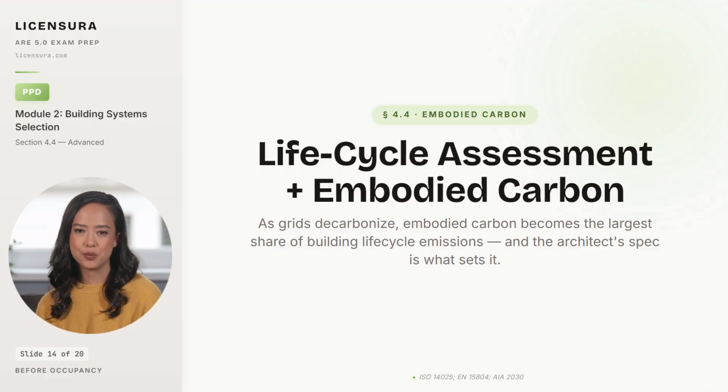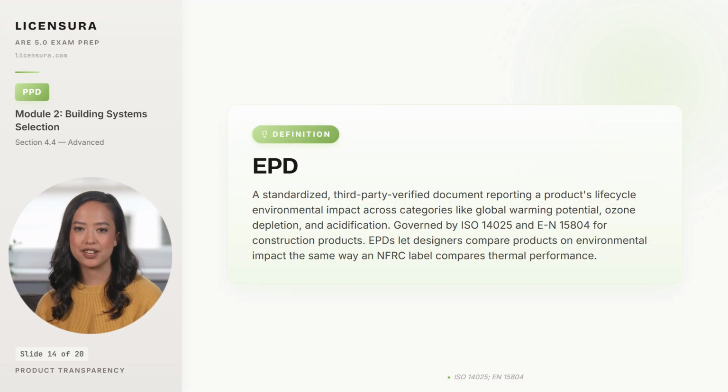Before anything else, one acronym does the heavy lifting in product comparison. The Environmental Product Declaration, abbreviated EPD, is the single document that makes comparison shopping for low-carbon materials possible. Without an EPD, every manufacturer's marketing claim is unverifiable. With an EPD, you have a standardized, third-party verified report covering global warming potential, ozone depletion, acidification, and a handful of other impact categories, all measured by the same methodology against the same boundaries.